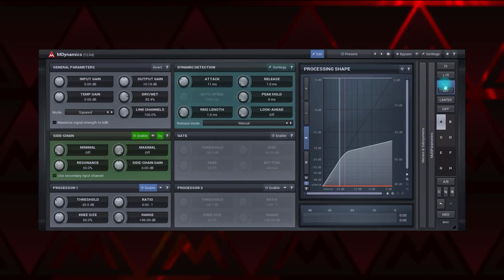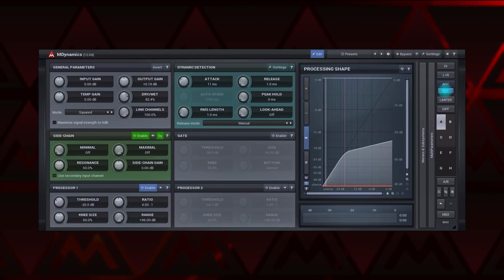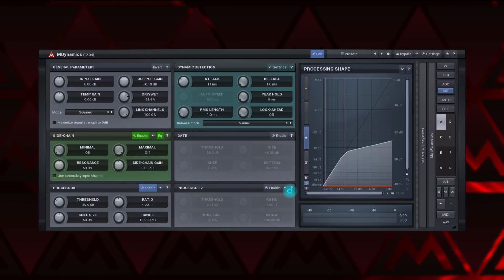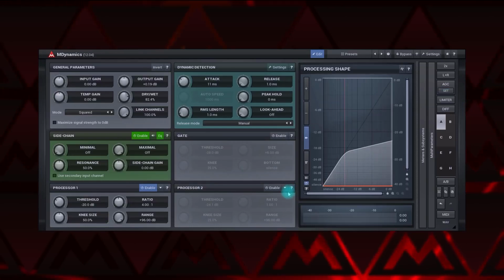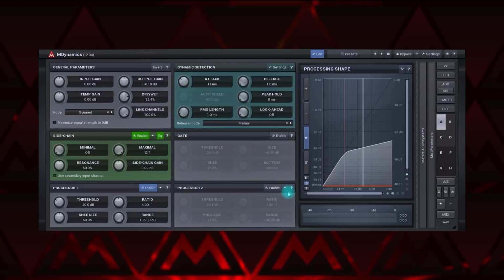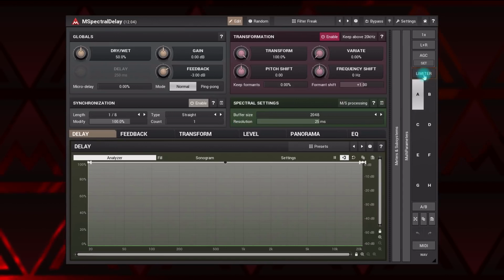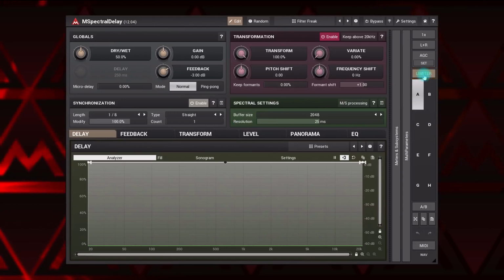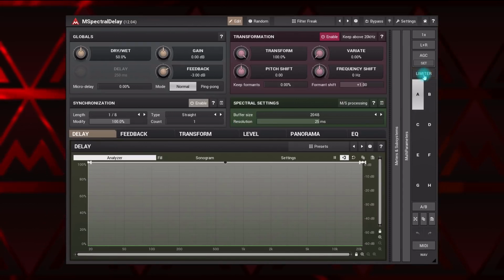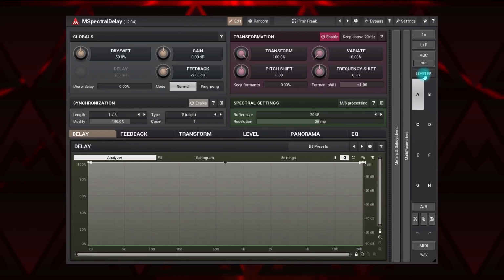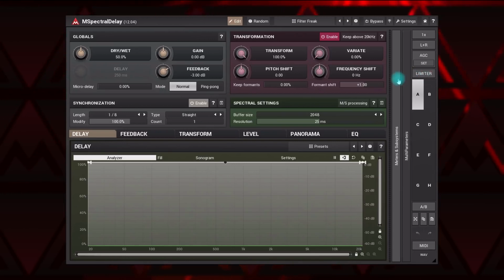There it may often be better to use the Set button, which usually is available inside the AGC button, and which changes the main output gain parameter of the plugin instead of having a complex AGC module processing the output all the time. The Limiter button turns on/off the safety limiter that suppresses high-level signals. Very handy solution when you want to experiment and keep your ears safe. It limits the signal from going over 0 dBFS.